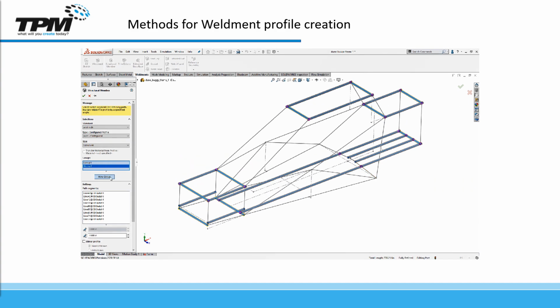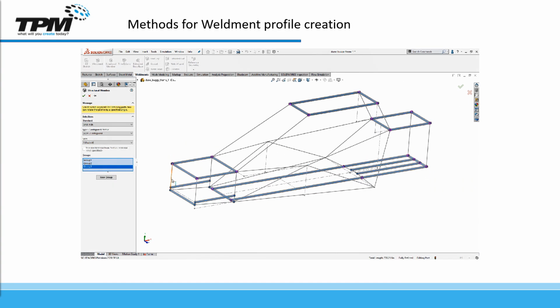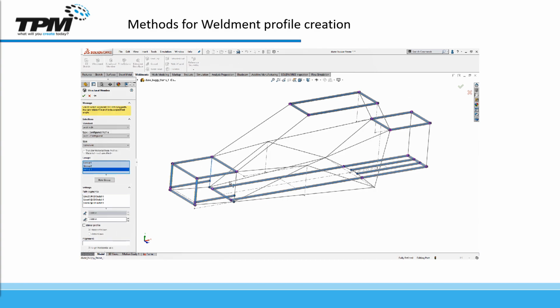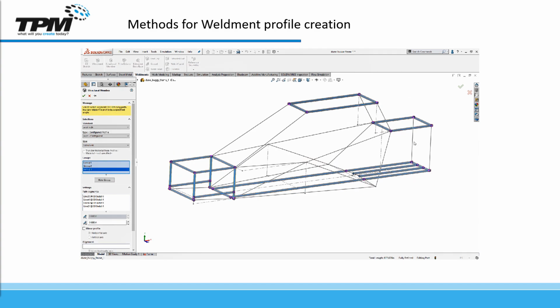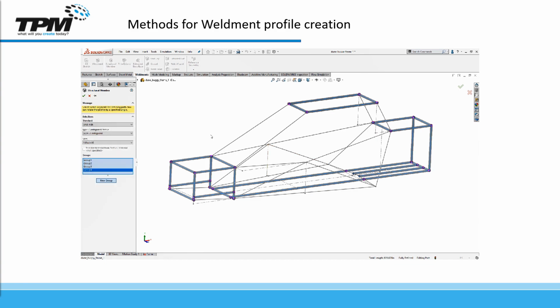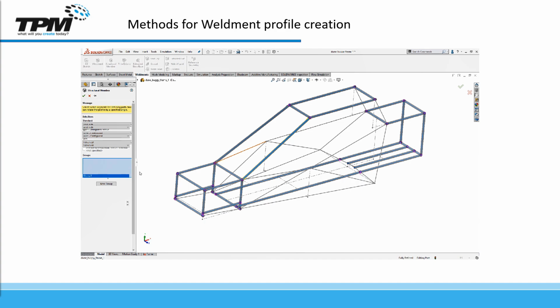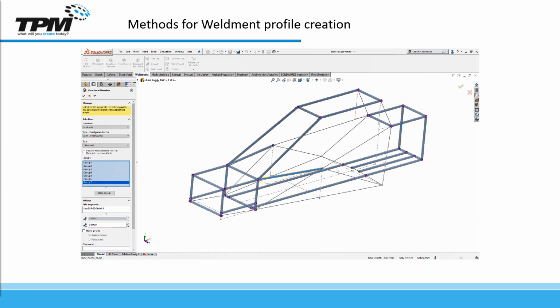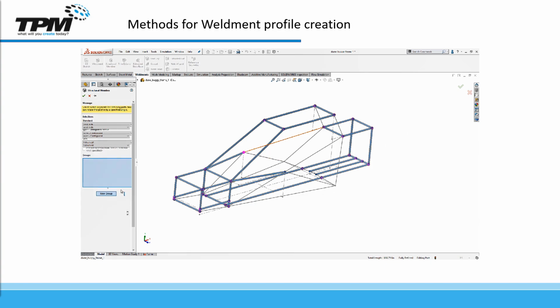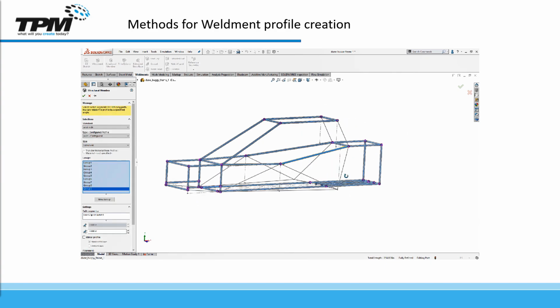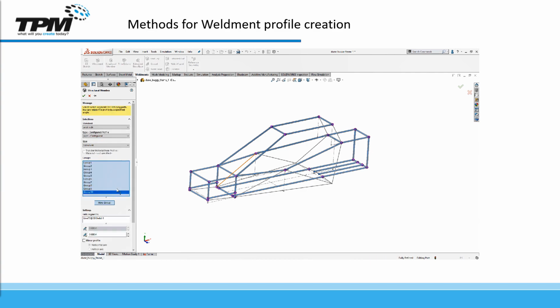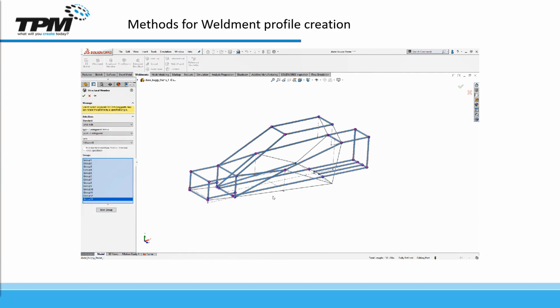So I'm working my way through my model here and picking out all the different groups that can be grouped together. So you notice I work from vertical members to horizontal members, and then I hit a new group. Once the horizontal and vertical groups have all been selected, I go to work on selecting the individual members that are unlike other members. These members have to be selected independently by SOLIDWORKS.